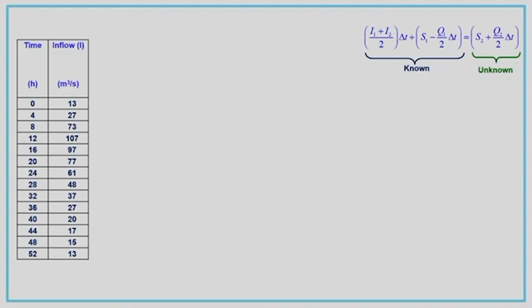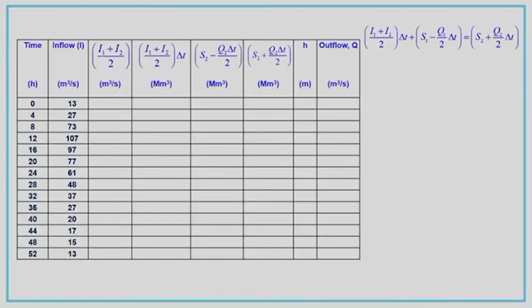So, with the known storage elevation data and the discharge elevation data, we have plotted a curve with the elevation versus indicative storage and elevation versus the outflow data. By making use of that curve and also the known data at time t equal to 0, initial values are known to us related to storage and outflow, and also the inflow flood hydrograph, we will further calculate the required values. So, this is the table required for us.